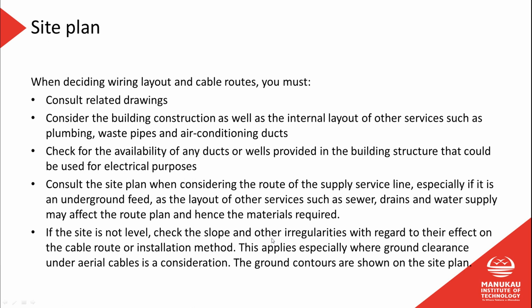We consider the building construction as well as the internal layout of other services such as plumbing, waste pipes, air conditioning ducts. A couple of things there. One would be isolation of services, not putting them on top of each other. That may or may not be a big issue. But we would need to think about access later.